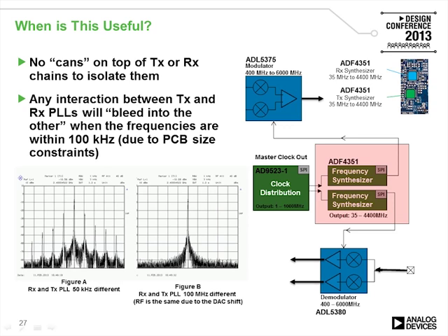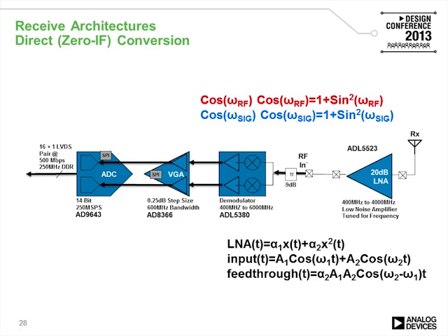When they were not 100 kilohertz of each other, because you could, for example, center shift the modulator or center shift the DAC, then you'd get a much better signal coming out into the LO that's going to be modulated, going up and being modulated. So in terms of receive architecture, we have essentially the same thing, just the opposite direction. We have potentially an external LNA, DMOD, VGA, and then ADC, where we still have our cos and our sine, just like we did before.